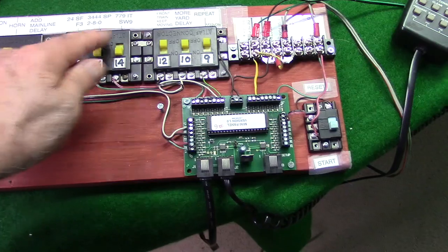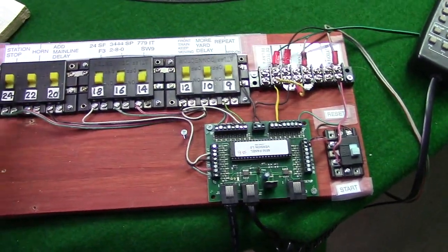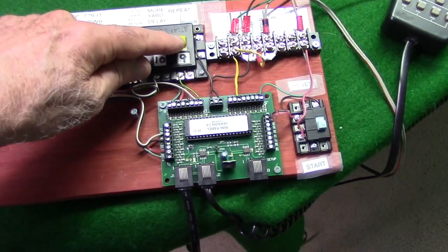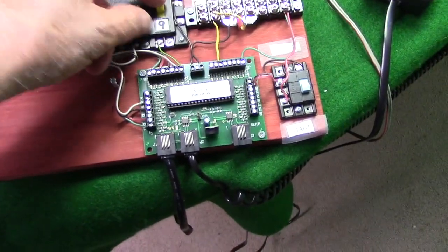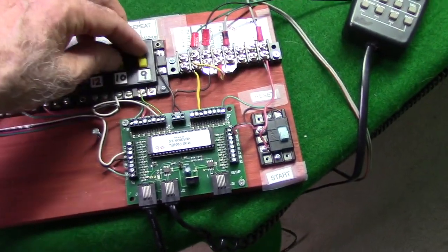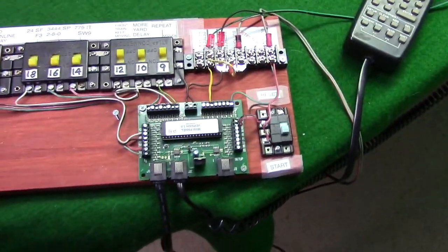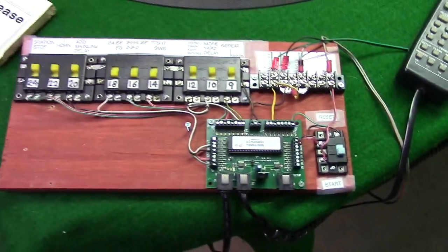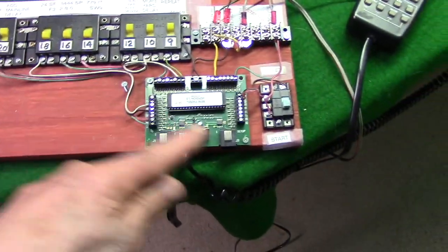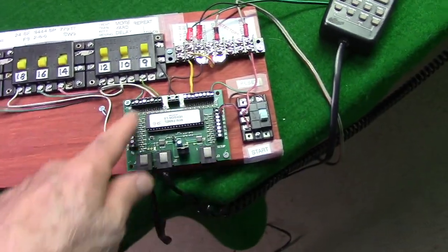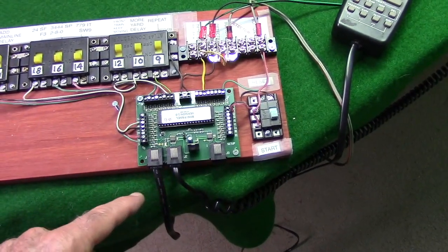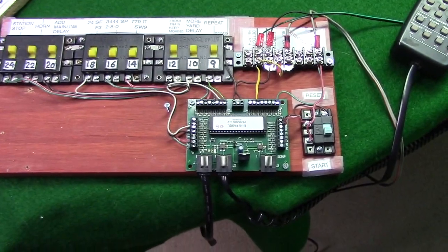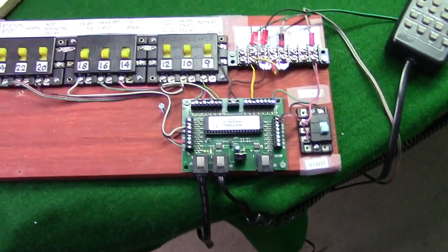These are Atlas number 205 slide switches, and when they're away from us, they're off, and if we push them in, like that, they're on. They make a constant connection, and all we're doing is grounding inputs. There's 9 of them, so we can ground 9 different inputs. And when this thing goes down through its programming, you can have it check inputs, and if the input is grounded, you can have it do one thing.